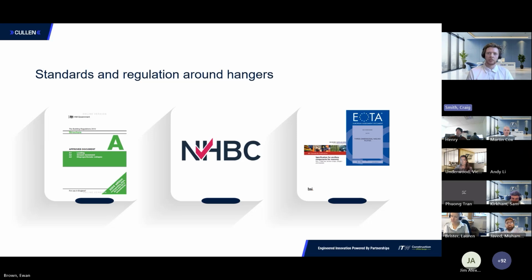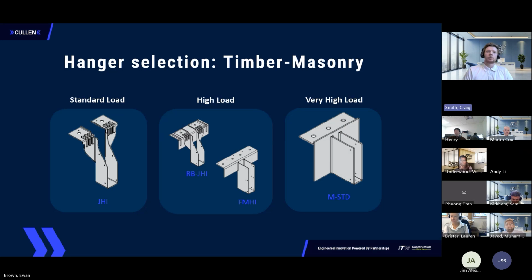The BS EN is for masonry, and these are just for component quality. While the NHBC logo is on the screen, I'll hint to this throughout the webinar, but just to point out that hangers must support at least 60% of the joist depth, and this prevents any twisting and ensures that the hanger performs as it should. That is an NHBC requirement.